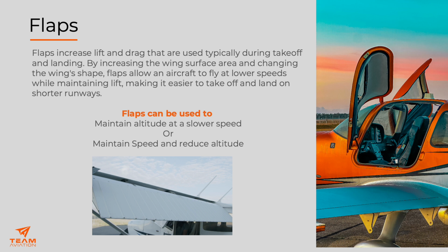Typically, there are a number of stages of flap that deploy the control surface to preset degrees. For example, this aircraft can deploy 3 different stages, including 10 degrees, 20 degrees, and 30 degrees.